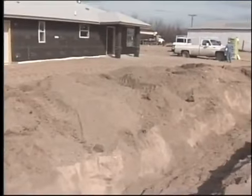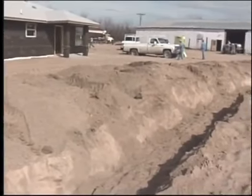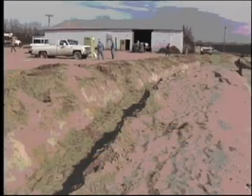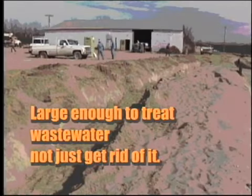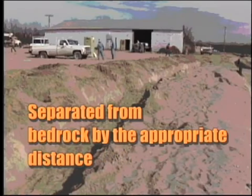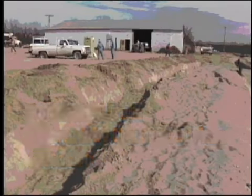To ensure long life of your septic system, the drain field must be designed using the correct soil type or soil absorption rate, large enough to treat wastewater, not just get rid of it, and separated from the groundwater and fractured bedrock by the appropriate distance.